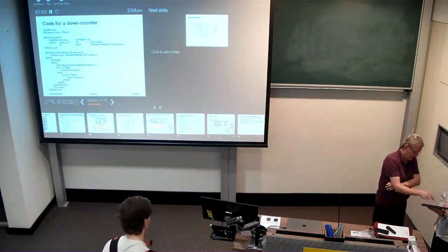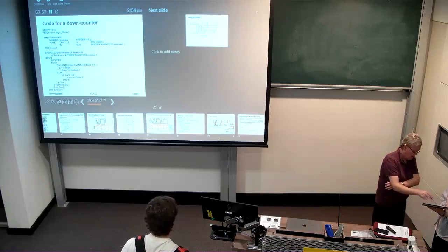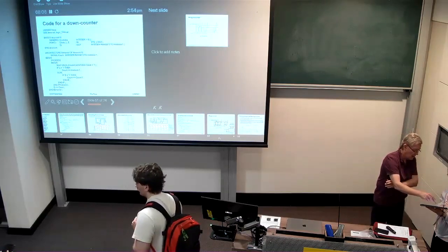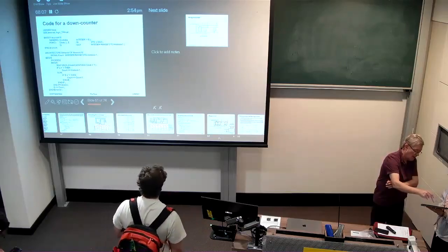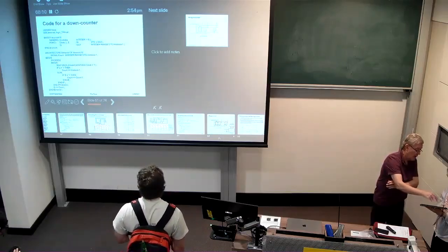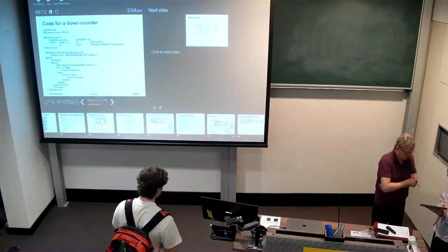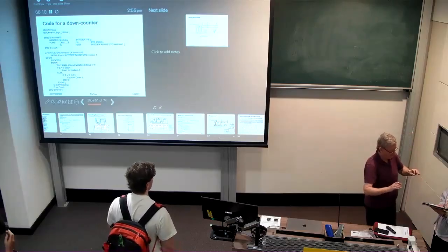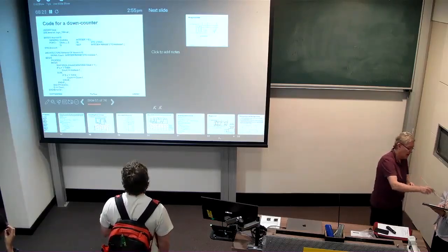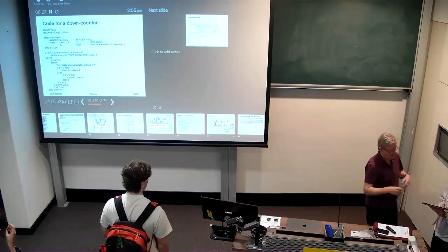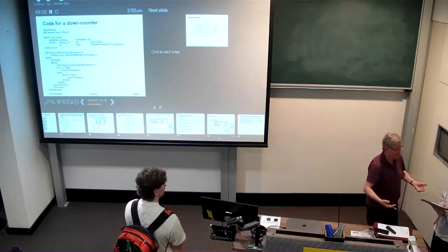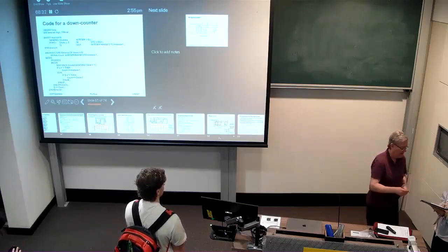But apart from that, it depends on the resistance and the capacitance of this gate as to how long it will take to change once P2 goes to 0 and if D were to change. And that may also be asymmetric. We're using very, very broad generalizations to say all gates change at delta time. The minutiae are a lot more varied. There are many factors that come into play.